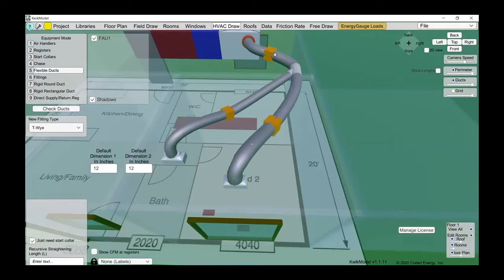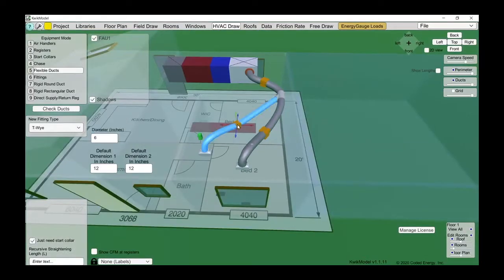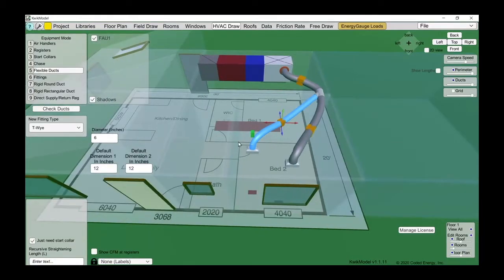We'll draw the ducts, we'll size the ducts based on the airflow, but in order to get our airflow, we need to know each room's load, and then we add those all together to size our equipment. And once we size our equipment, we can then determine an airflow, and that airflow gets distributed to the rooms, which is how we're going to size our ducts. Okay, so that's where we are. I was just going to give you a preview, so let me delete these teasers here.